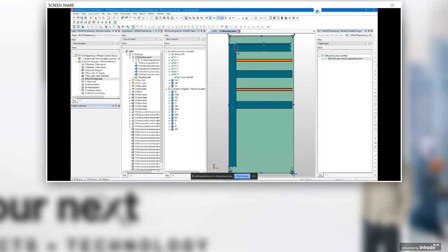Now to place my components on the back plate, I can select here, for example, my protection devices. Here I've got my motor overloads, 2 of them. I'm just going to use drag and drop to place them on here. I've got my main disconnect right here, so I can just drop it in here. I've got my contactors, just drag my contactors here. I'm just going to place them 2 at a time. And then I've got my terminal strips that I can just drag and drop and place on this bottom rail.